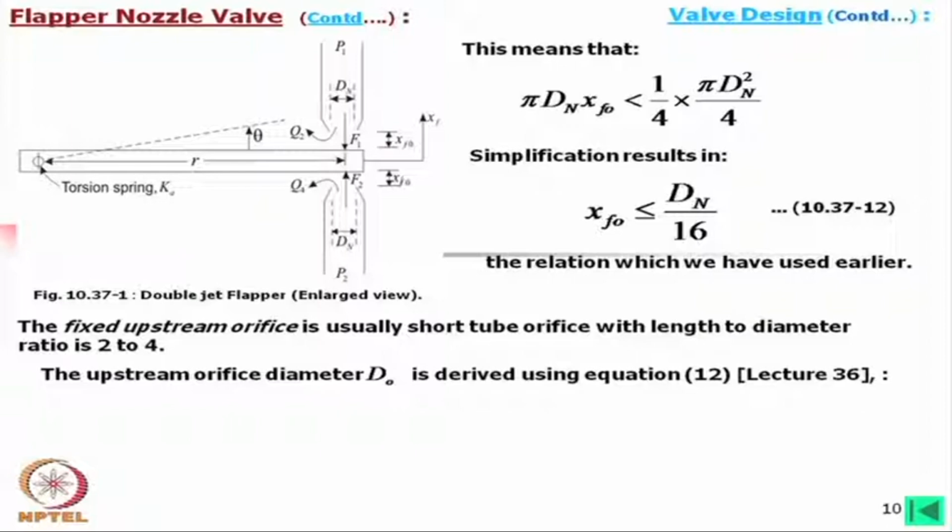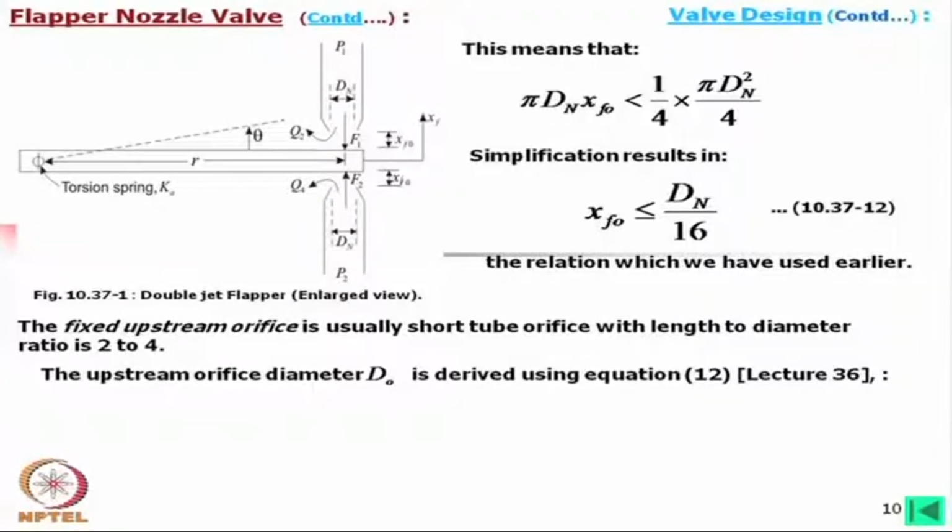But usually you find a very thin plate and a very small hole is used, usually a straight hole, in some cases also a hole with an inclined entry or maybe a distal side. Normally a straight hole is the best. Now, from this diameter and length ratio, we can find out the coefficient there. There are different models, but we will see some realistic data.